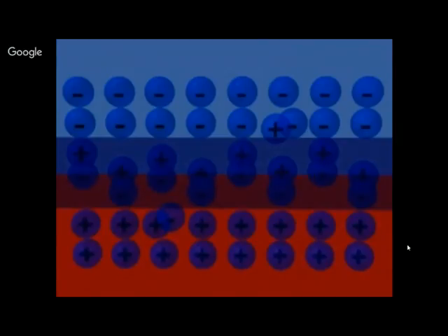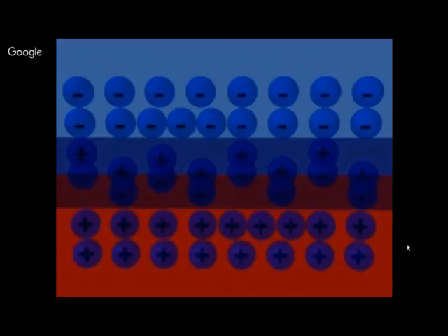If this happens in the electrical field, electrons are moved to the N-doped layer and holes are moved to the P-doped layer. The system will fall into a state of imbalance because of an excess of electrons in the N-doped layer. The corresponding holes can be found in the P-doped layer.